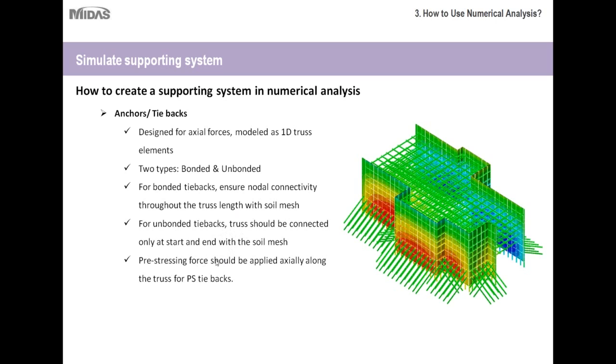And then, of course, pre-stressing force should be applied axially along the truss for pre-stressed tiebacks. As far as pre-stressing forces, most programs have a special feature for that where you can model it. GTS-NX has one as well, where you just enter your pre-stressing, select your elements, and then it'll be applied to those elements.